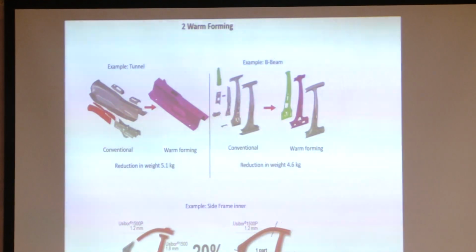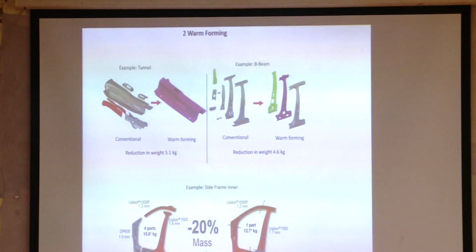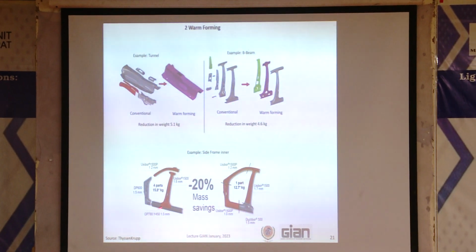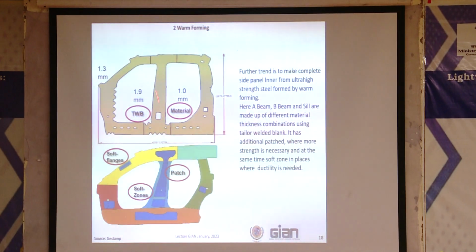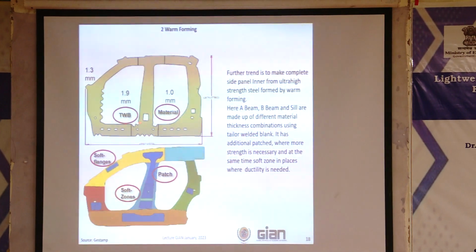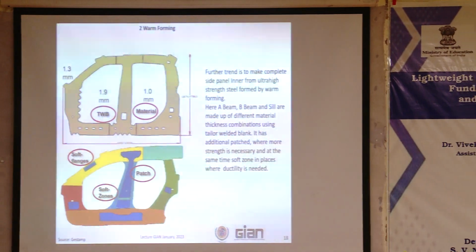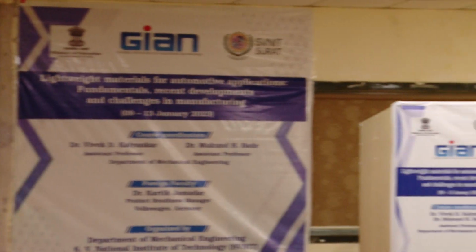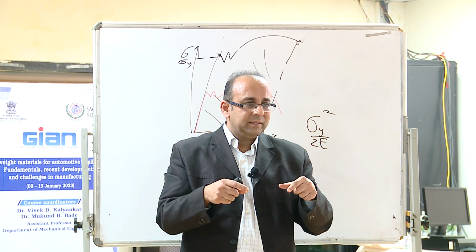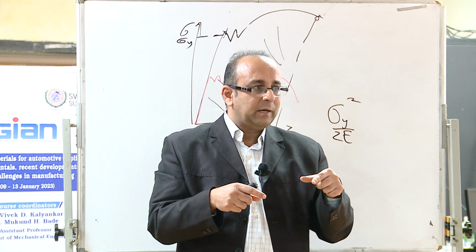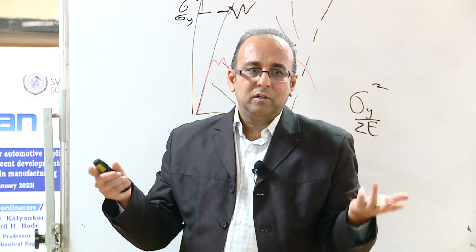So basically, just what I said, initially we had all different parts together. Like the example I told you, 1 part, 2 part, 3 part, 4 part of different thickness one can make, but I have to make 4 parts. 4 parts, 4 toolings, joining, everything, problem. So let's make it 1 part, but the 1 part thickness would be determined by the highest thickness, not feasible.